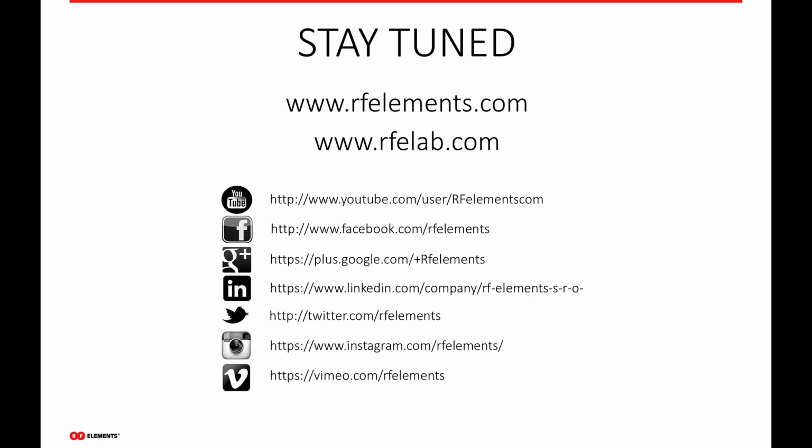Again, a smart antenna is an array of antennas typically, right? It's a beamforming antenna where it has multiple antenna elements that are working together with a single radio, which is the important part, with a single radio to be able to direct the beam in a certain azimuth, right? So a horn antenna is totally different. It's a single radiating element on a single radio. So there really is no direct comparison other than single radio, single beam with a horn, and then the smart antenna is an array of multiple antenna patterns within one enclosure. I hope that answers it.